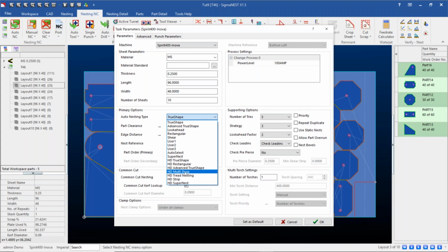Instead of using the common cutting as the standard sequencing, it will group some parts in a vertical line across the sheet, and then sequence it so that as it's cutting the last edge, it cuts the last edge of all the parts at one time, so the trap door can open at the same time